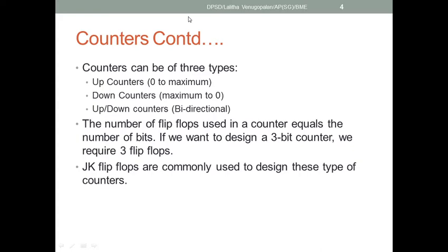Now, the number of flip-flops required in a counter equals the number of bits the counter is designed for. For example, if you want to design a 3-bit counter, you need 3 flip-flops. Very commonly, JK flip-flops are used in counters.